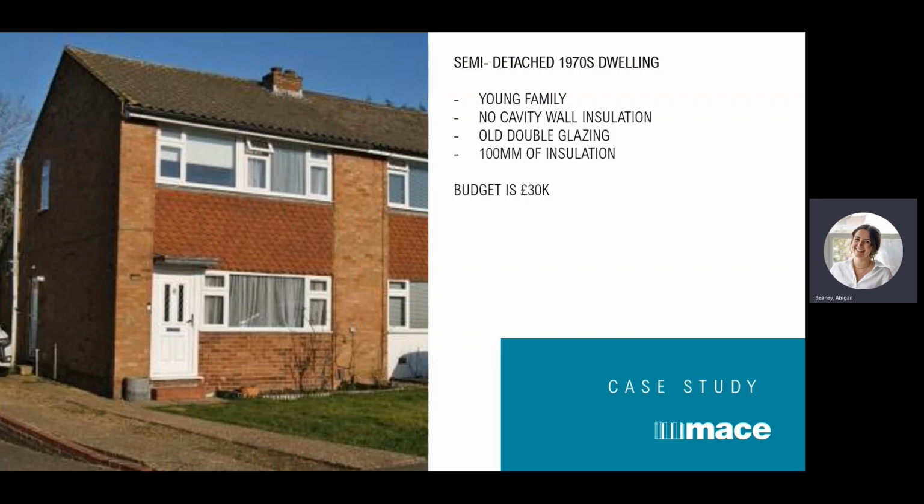We can be looking at the performance of that double glazing. When was that installed? Does that double glazing have trickle vents? Do those trickle vents need to be retrofit onto these, or are the windows blown and need replacement? That would be a good exercise to understand and help with the performance of this dwelling.